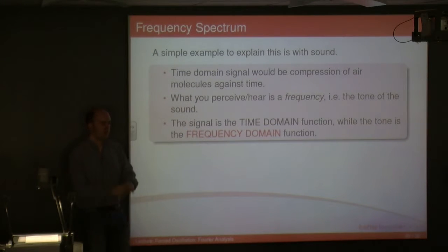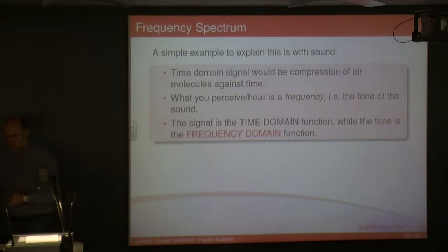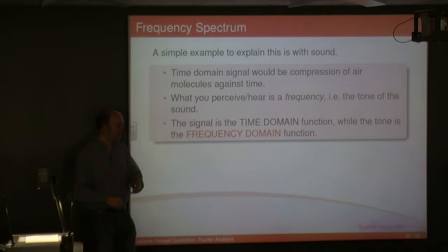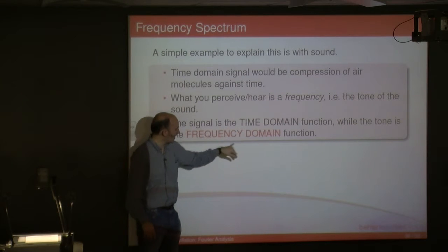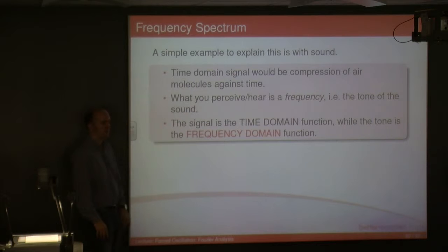Okay, so even if you're in a soundproof room, the only thing that's vibrating the air molecules will be that instrument. The time domain will look different, because a violin sounds different from a piano. And it's the same thing if I say ooh, that's different from ah. It's a different shape, but it's the same note. So when you convert that time domain to a frequency domain, you'll get the same peak at that certain frequency.